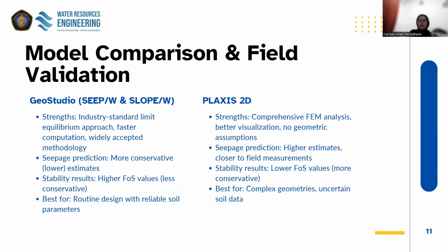And for the model comparison and field validation, for the GeoStudio, it has strengths for the industry standard limit equilibrium approach and faster computation, a widely accepted methodology. And for the seepage prediction, the GeoStudio is more conservative with lower estimates. And for the stability results, the GeoStudio has higher safety factor values, so it's less conservative than the Plaxis one. And the GeoStudio is best for routine design with reliable soil parameters.